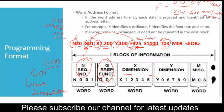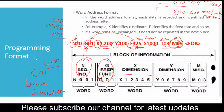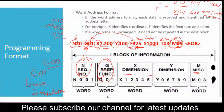Okay, M09, sorry, just a moment. M09 stands for, M stands for miscellaneous code, and 09 along with M stands for coolant off. M08 stands for coolant on. So that is nothing but a miscellaneous code. And EOB stands for end of block.